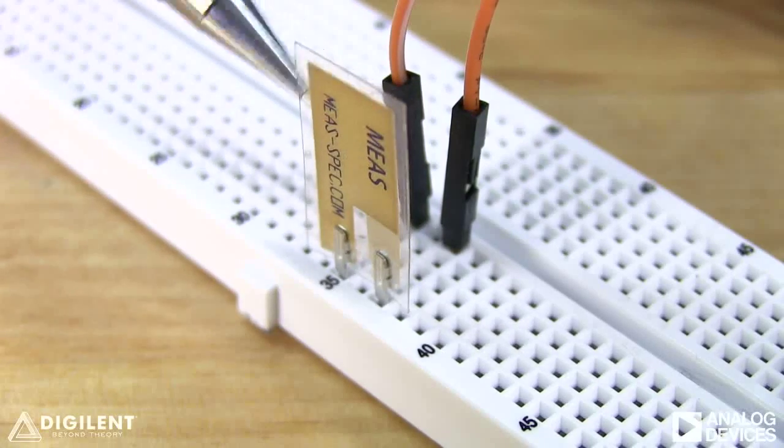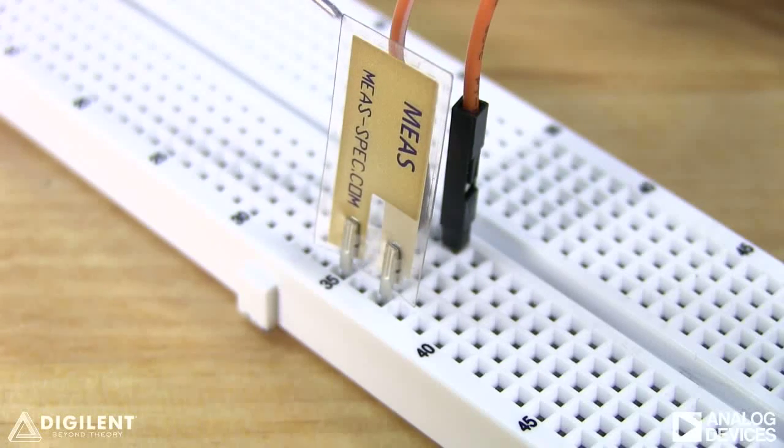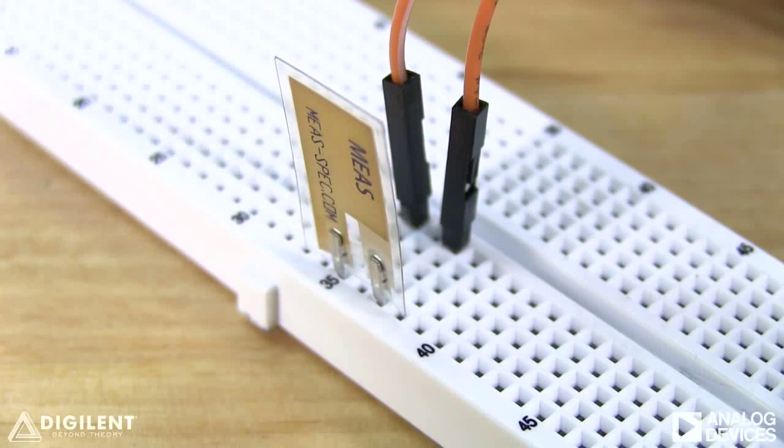So far, we've only talked about continuous data acquisition. The data is always being acquired as long as the Run button has been clicked. Sometimes, we want to acquire only a single window worth of data. We'll use this piezoelectric sensor to illustrate use of single sequence acquisition. Our piezoelectric sensor outputs a voltage difference between its terminals when it's bent. These sensors are often used in vibration measurement.